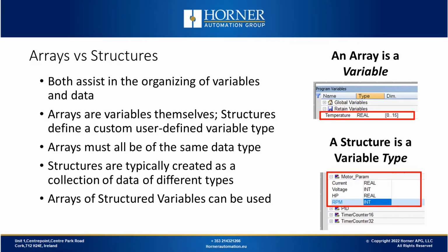Now let's compare arrays and structures, as they're very similar but different. So both arrays and structures can assist you in organizing your data. Arrays are variables themselves, so you would directly reference arrays in function blocks, screen objects, etc. Whereas structures define a custom type. When you create a structure, you're creating a custom type, and then to access it, you need to create variables that use that custom type or use that structure.